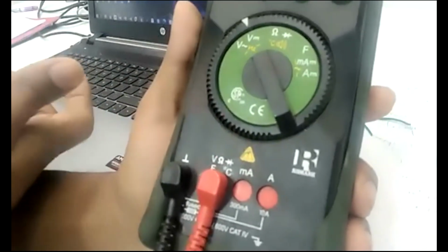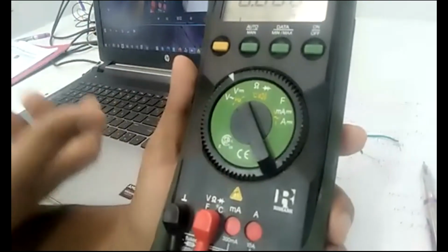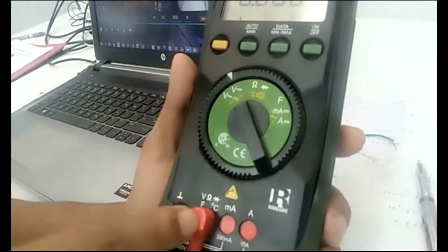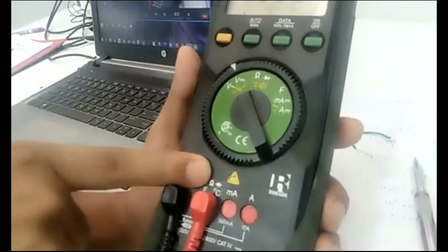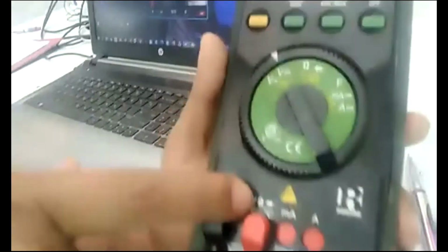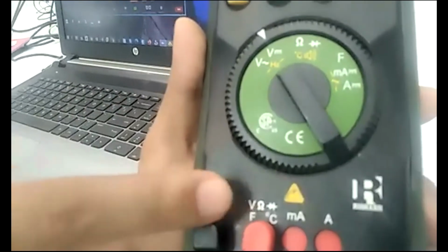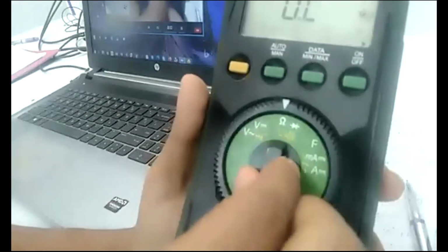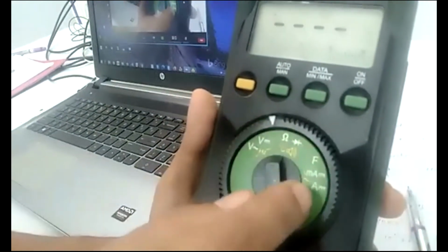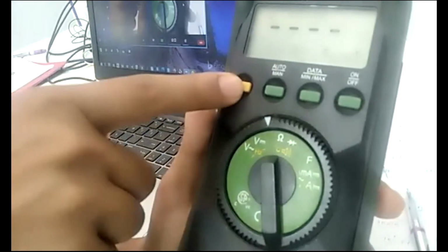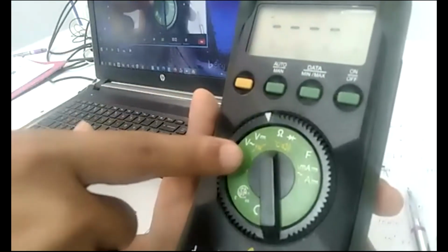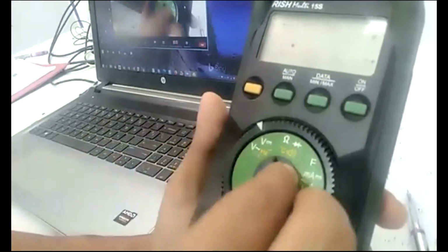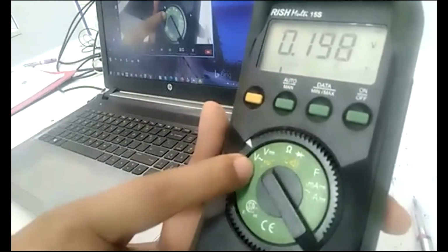If we want to measure voltage, and ohm meaning resistor, and capacitance value, we have to connect in this port. Also if we want to check the connectivity or measure a diode, then you can observe that there is a diode symbol. We have to connect it over here. If we change it over here, you can observe something is written in white and yellow. Depending on this, the yellow option will be affected. Let's say this one is V in AC form, so AC voltage.